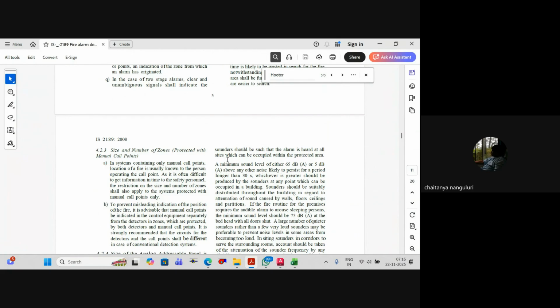Yesterday, you remember I told you you have to give a minimum of around 75 decibels. Yes or no? Yes. Yesterday, while explaining the hooters, I told you 75 to 80 decibels is what you have to provide in any space. You remember it? Yes, sir. Okay, but here it is 65 decibels. Let me complete it, then you'll understand why I said 75 or 80.